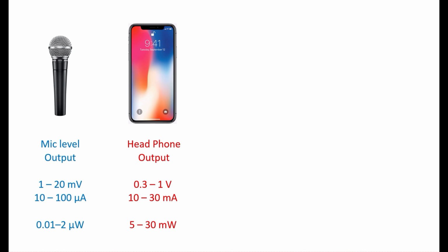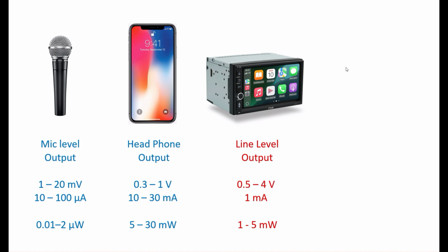to speakers. And if I look at a third example, such as an unamplified Android head unit, once again, half to 4 volts, 1 milliamp, 1 to 5 milliwatts of power. These are line level outputs designed to feed an audio signal into a DSP or an amplifier or something like that, not strong enough to directly connect to your speakers, right?